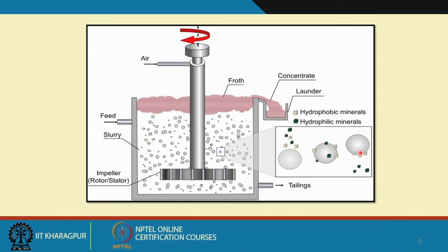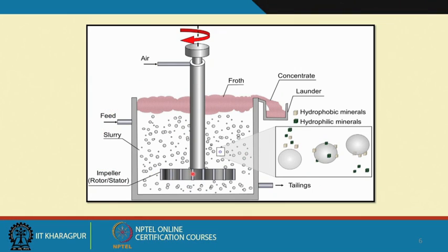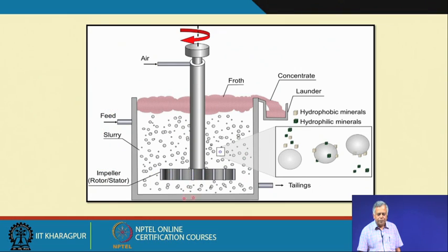So, this is in short how it works, but having described it, you can understand how difficult it is to control everything. What are the things we have to take care of? First, the impeller: at what RPM it should be rotated, what the design of the blades should be, what air pressure I should have, and what the dimensions of the perforations should be.